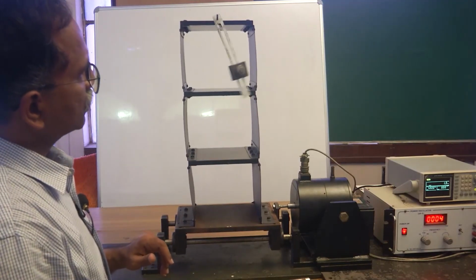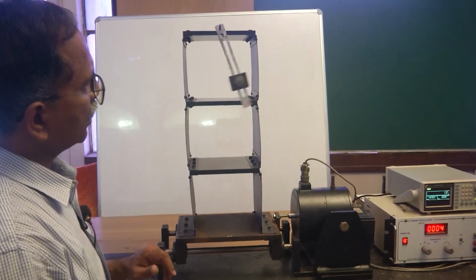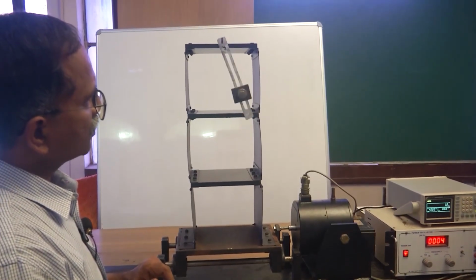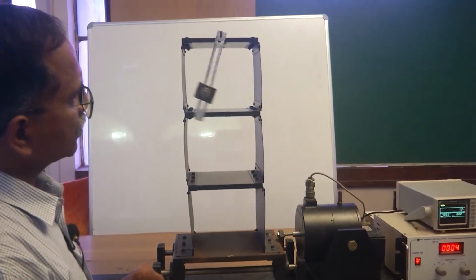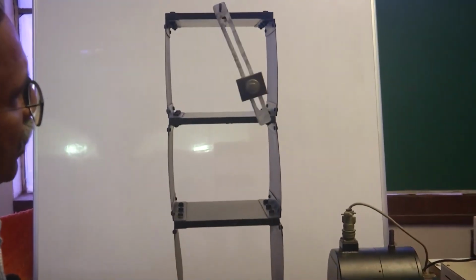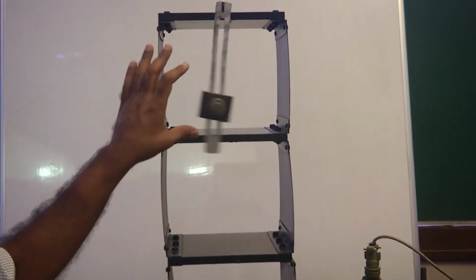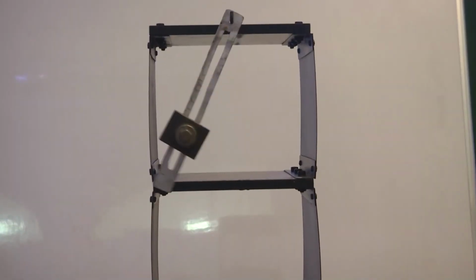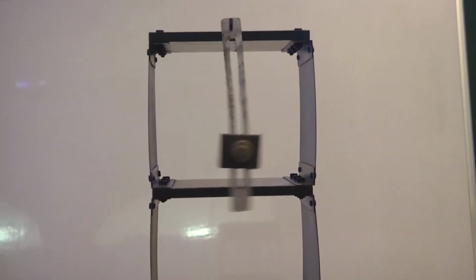So what I am going to do here is to attach this pendulum and see if the parent system vibrations are brought to 0. You can see that compared to when the pendulum was not there and the system was vibrating at its first natural mode, the amplitudes were very large. By attaching this absorber, you can see that the vibrations are of course not exactly 0, but they are much smaller as compared to when it was not there.